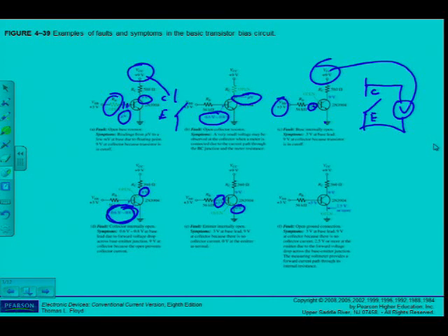In other words, the base emitter voltage should have been approximately 0.7 volts. But I do get 3 volts, and the track seems to be fine up to the base. But it means that the emitter then is internally open. Still have the 9 volts there, so it means that the transistor still is in cutoff. I still measure VCC between collector and emitter.